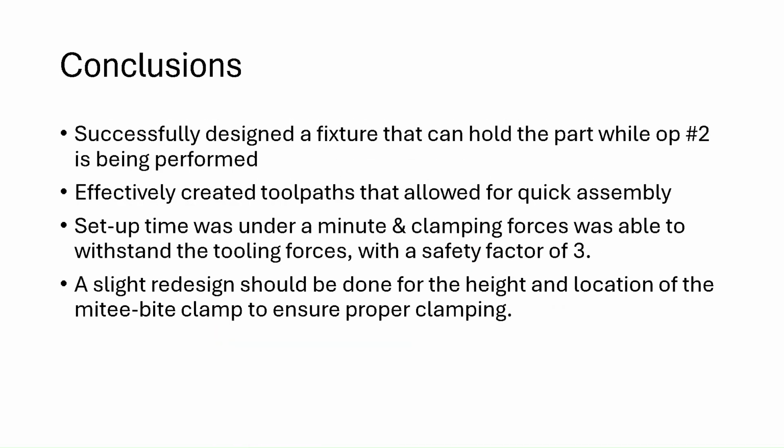In conclusion, we were able to perform operation 2 and get a successful part. We were able to have toolpaths that did not collide with any of our components. We had a setup time of under 1 minute, and our clamping forces were stronger than our cutting forces with a safety factor of over 3. And a note for future designs: we will move the clamp location closer to the part.